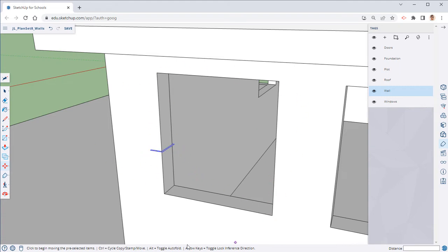The window is going to go all the way around. The Follow Me tool tends to mess up if you have your shape down in a corner, and it will not finish all the way around like you want it to. It looks funky there at the very end. So if we move it up here to the center and off of the corner, that negates that issue.